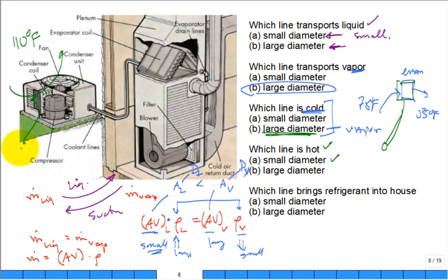It has to be greater because it's dumping heat to the air that's at 110. The air that comes out may be 115 or maybe 120. I don't care what the air is that blows out the top. But the refrigerant inside probably is around 130 degrees F. It could be toasty. That's what's in the liquid line, ready to go back up inside your house. So, yeah, you can sense it. It'll be warm.